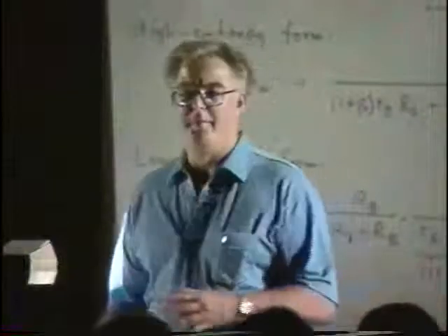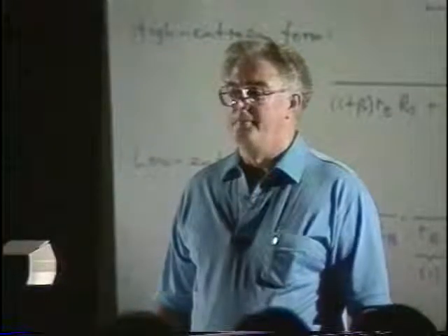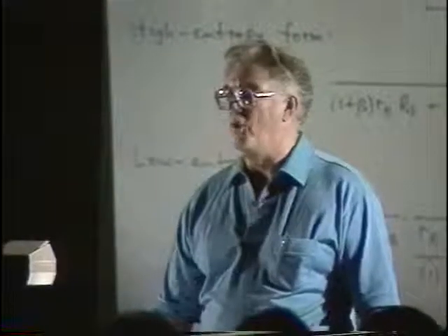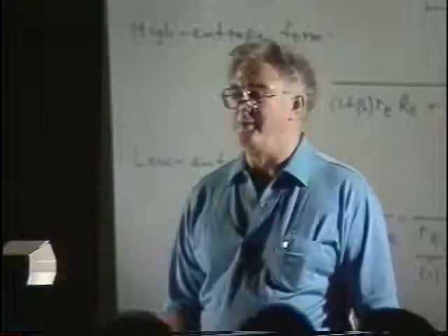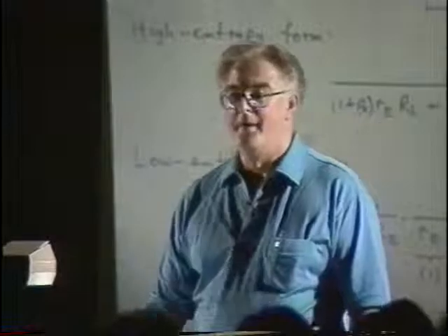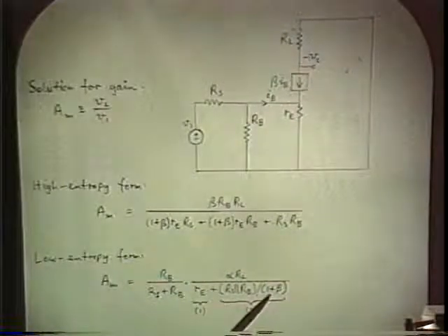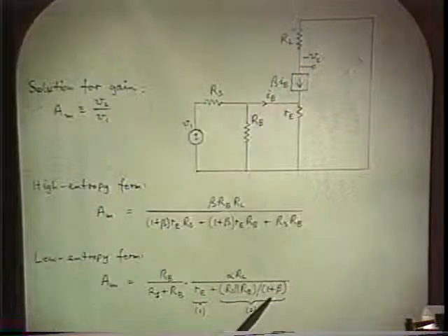You know parallel combinations are dominated by whichever one is smaller. So when you need to change values, you know which ones to change and in which direction. That's extra useful information.